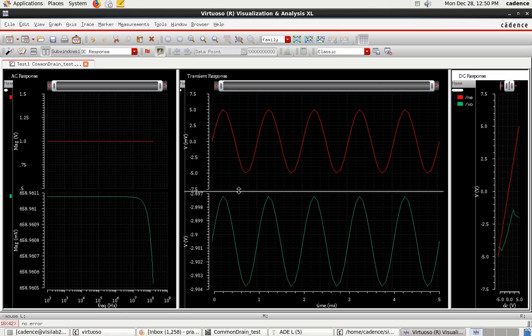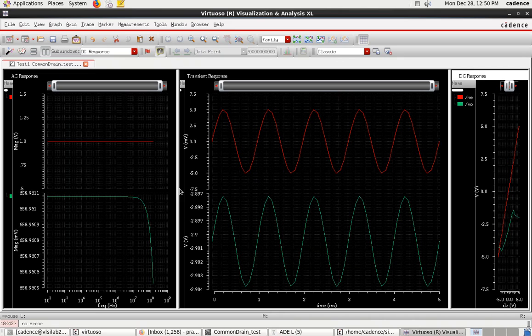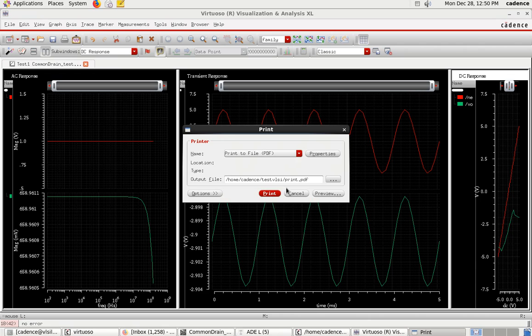Now, if you want results near to the pre-layout simulation results, you have to go back to your layout and perform the area optimization once again. Then you have to come back and perform the simulation again by extracting the parasitics, so you may get the expected results.